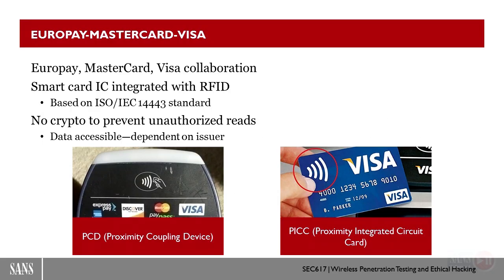All right, so looking at some of the electronic transactions for EMV, Europay, MasterCard, and Visa. The ability to have a contactless card for use for payment. So again, similar type of technology that we saw with low frequency in that having the devices embedded into a card form factor, but in the high frequency range with the ability to do fixed IDs and additional data as opposed to just a unique number. Typically, we're finding most of the applications around the high frequency stuff in the ISO 14443A and B standards.